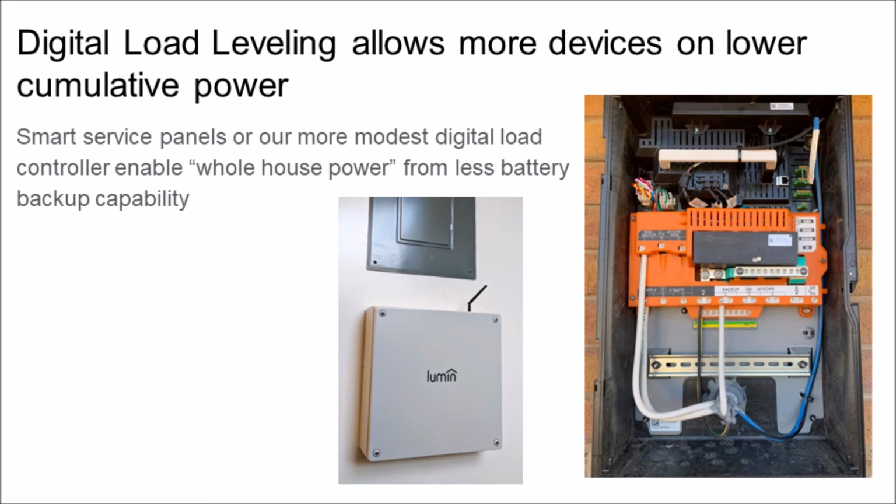But the best solution would be to install an automatic transfer switch between the home and the grid, and then manage the home's electrical load to operate within the parameters of the battery inverter such that the entire home can remain powered up during that outage, just at a lower energy mode. So some of these companies control and monitor every load on the electric service panel, and some just do a portion. And the end result is an expensive system that might also add value to other more expensive things already on site.